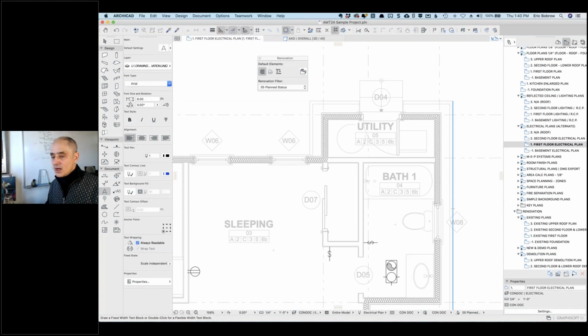Okay, so Dave says, if a wall is demoed for scheme 1 but not scheme 2, that's a limitation because you can make it show up in scheme 1 or scheme 2, but you can't change whether it's demo or not. It just doesn't work that way. So then you would possibly use layers. And you could have a layer for scheme 1 and a layer for scheme 2, and that'll work okay, but you will probably want to put the walls and the roofs and the furniture, etc., all on that layer. Otherwise, you're starting to get several layers for scheme 1, several layers for scheme 2, etc.